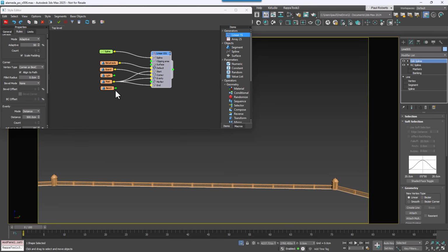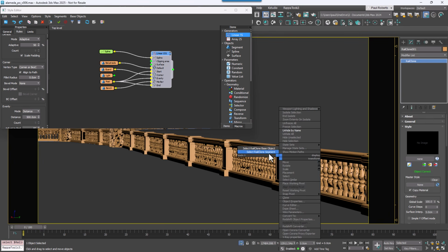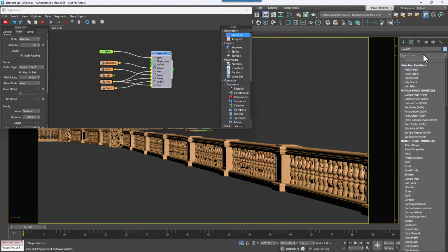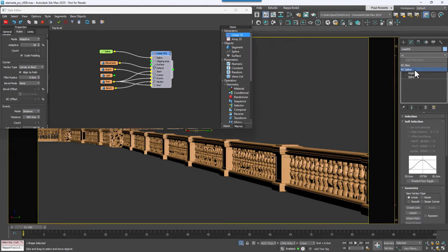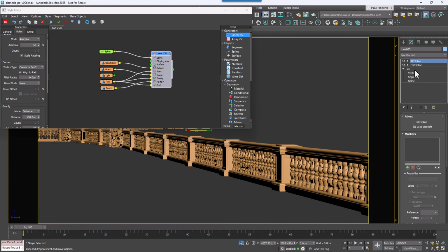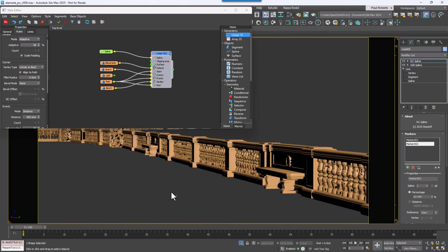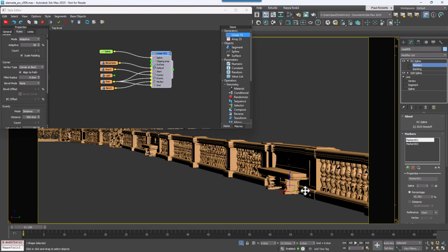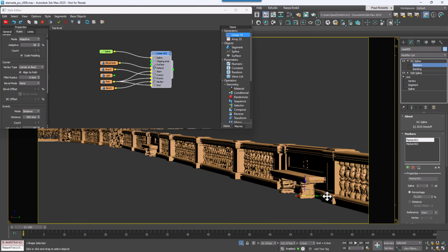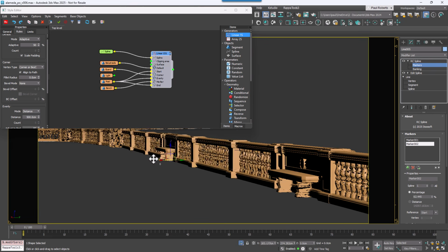So to add the benches using these markers, connect the bench segment to the marker input of the generator. Select the spline in your scene. Add the RailClone marker modifier, found in the modifiers list, and then in the modifier settings, click the Add Multiple Markers button and click on the spline where you want a bench to appear. If you want to edit the location of the bench, you can go to the Markers sub-object level and use Max's Select and Move tool to easily make adjustments. You can move, delete or reposition any markers at any time to fine-tune the layout.